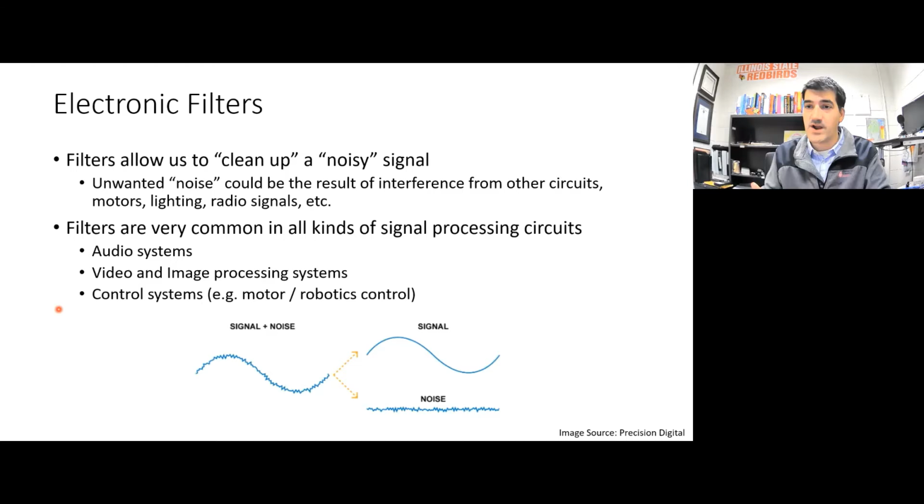That's a noisy signal. That's a signal where the desired part of the signal is relatively weak compared to the undesired part of the signal. In the case of that specific example, that's a lot of high frequency noise. Static tends to have a lot of high frequency components to it. So you would want to use a low pass filter to get rid of the static. But there are plenty of other cases where you want to get rid of the low frequency part of the signal. That part is undesired, and you want to only have the high frequency part of the signal. So there's lots of different applications for low pass and high pass filters and other kinds of filters.